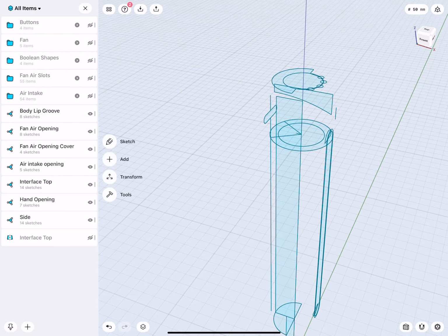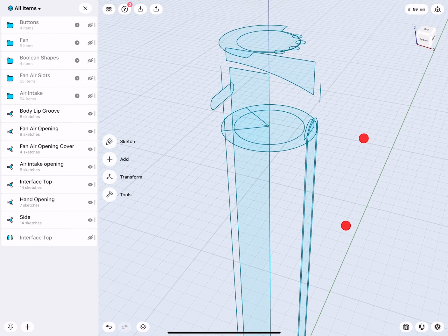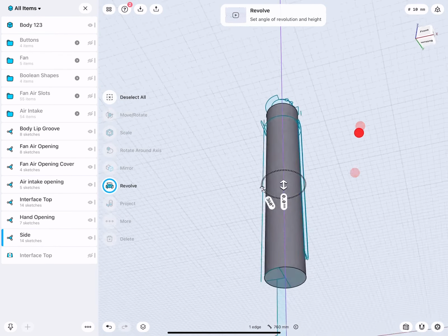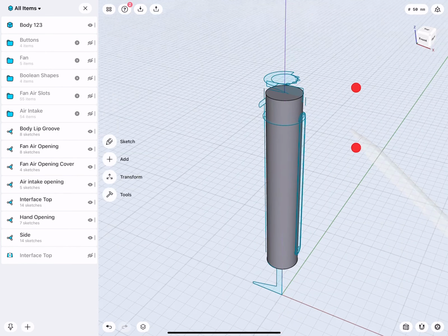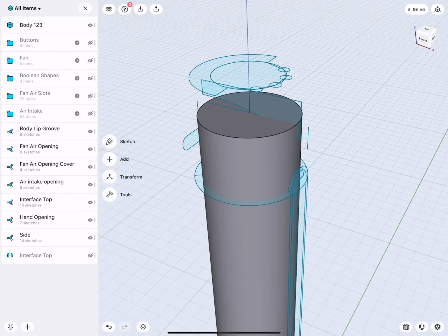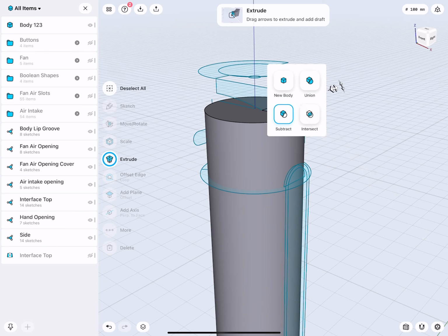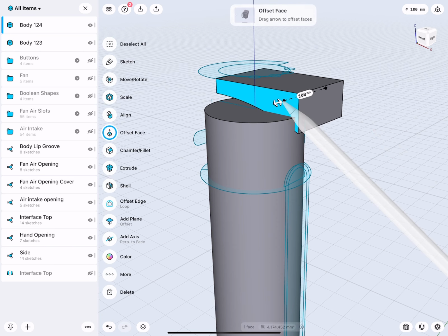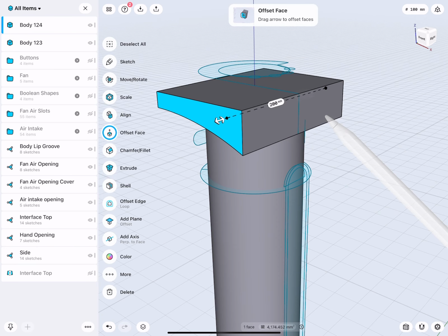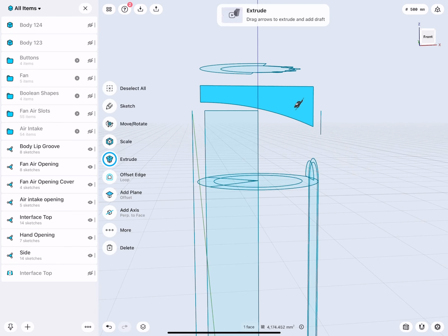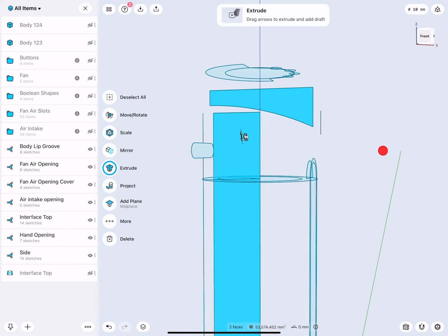So the fan is a cylindrical object. Okay, so that means, first thing, I will build a very basic cylinder. Very good, that was easy. The top of the fan is slightly arced. So I have this shape here, which I will extrude by 100 and then say a new body. Very good. Select this face and then I set this to 200. So you might ask yourself, why is the sketch not at the right position? Because it has to go a little bit lower.